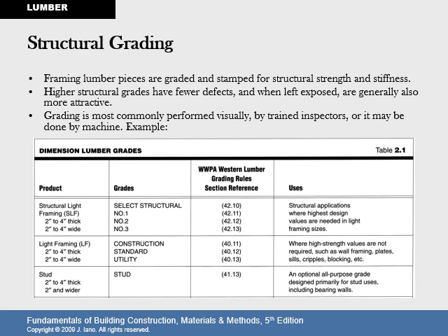You can see that framing lumber pieces are graded and stamped for structural strength on this chart. Higher structural grades have fewer defects and, when left exposed, are generally also more attractive. Grading is most commonly performed visually by trained inspectors, or it may be done by a machine. What you get is what you pay for.